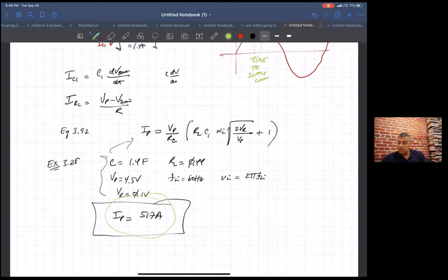So basically at this point, you see this is really not a good idea when you have something that's pulling a lot of power, or 25 watts was this. To live with a ripple of 0.1 volt on that thing is a real difficult problem, because you have a huge peak current that's going to blow up most diodes, or you have to get an extremely large, expensive diode, and you have a big capacitor, et cetera. So it's not a good design.